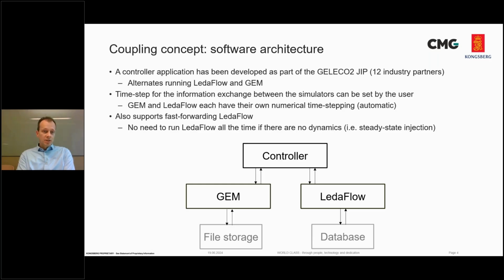The controller also supports fast forwarding LedaFlow in case you're running a very long simulation in GEM, maybe for a time horizon of several years. Then it's possible, for periods of time, to turn off LedaFlow, so you don't have to simulate all the time. This leads to quite a saving in calculation time.